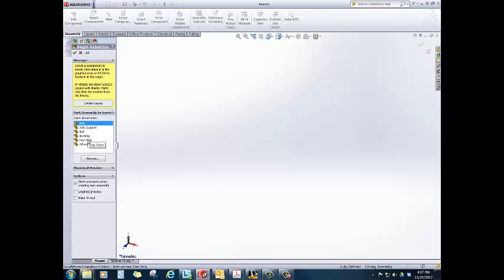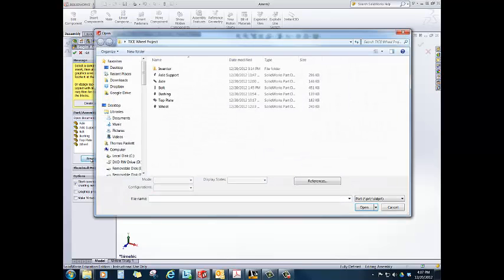Now if I chose to not have files open and went directly to creating an assembly drawing, I could use the Browse button and go to the file location and the path through that file to locate each of the parts needed and open them one at a time. Again, this makes several steps required to do the assembly, but by having them all pre-open, I can skip each of these steps.